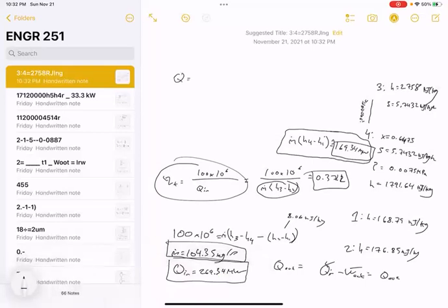So Q equals 169.34, which is what we just found. And Q equals m c delta T, right? Or in this case, m dot. c for water is 4.18-ish. And delta T is 20 Kelvin or 20 degrees Celsius, because we're going from 15 to 35 degrees.